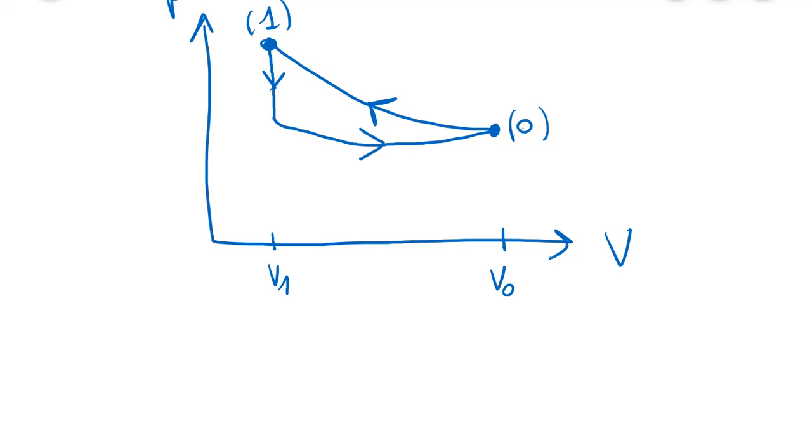As you can see, the adiabatic shape and the isothermal shape are very similar, but there is a difference. The curvature is more pronounced for the isothermal case. So I'm just going to specify everything. This was the adiabatic. This is the isochoric. And this is the isothermal. So this is the Clapeyron diagram for this question. Obviously, this is P1 and that is P2. And this is P0.